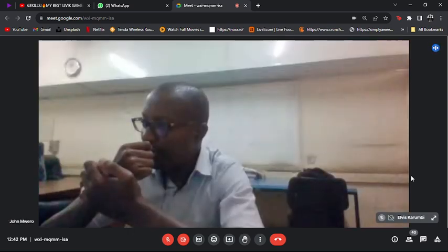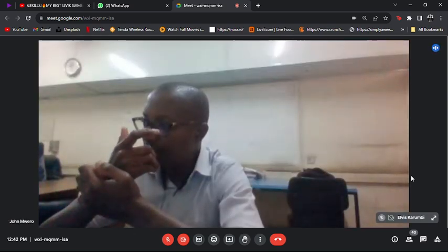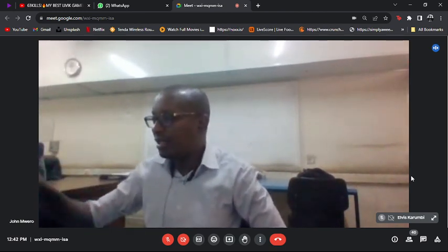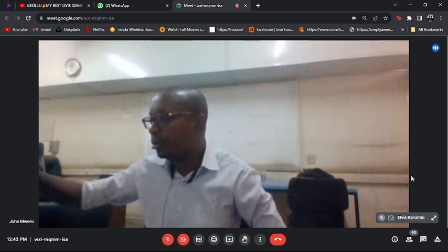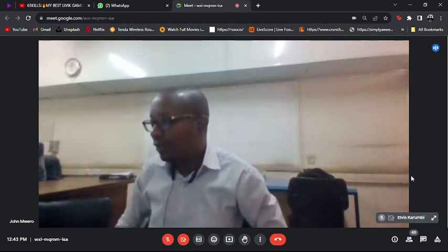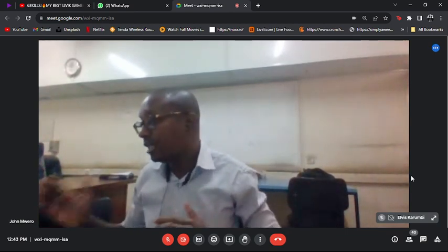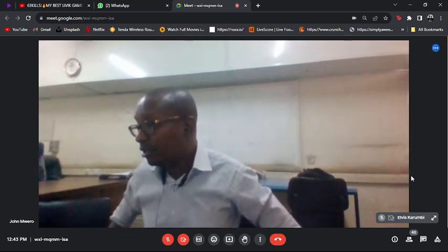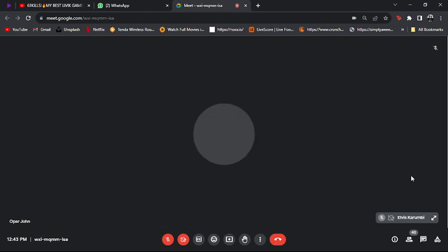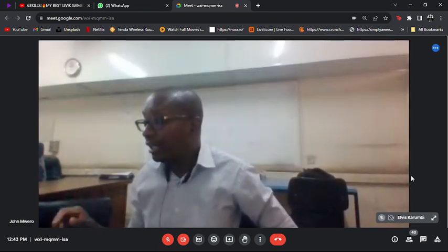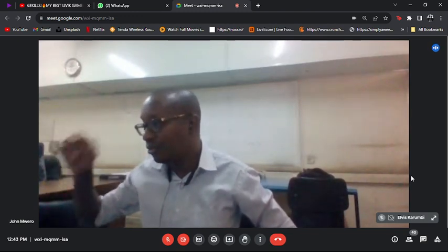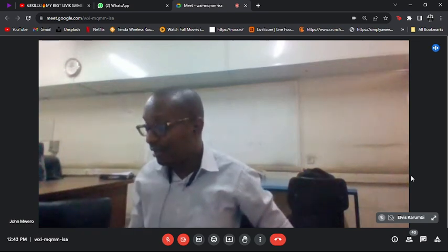Yeah, I mean, you can do that, but that calculation will be a bit more difficult than just saying WL squared over 6, and instead of L being 5.4, you put L is equal to 5. This is a lot easier if you did it that way, if you wanted the moment at the place where this wall would actually fail. You understand? Than to do the fancy integration thing, to do the curve and then to do this integration.